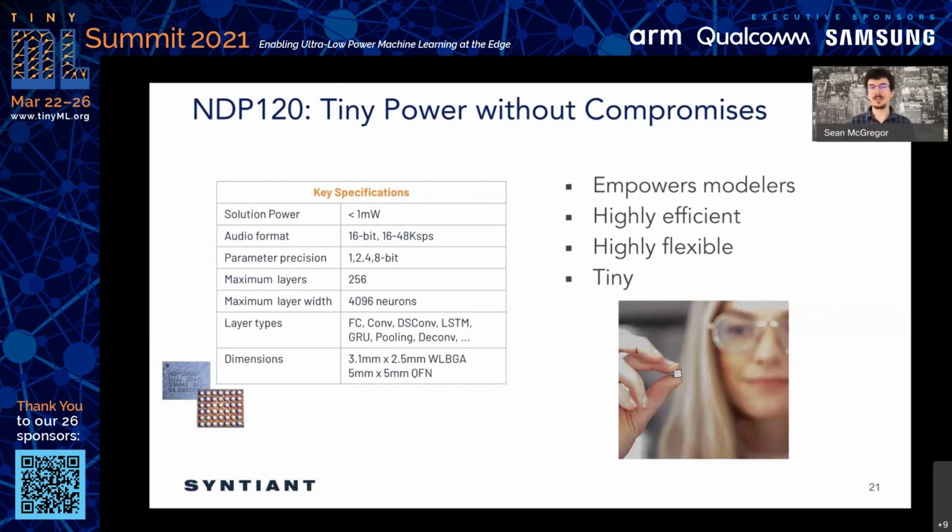If you find that you want to increase the model size to use a little bit more of the footprint in the NDP 120 that's in there, you can say the input layer runs at 8 bits, which input layers often need to be at higher precision, and then you can push towards lower precision in the later parts of the network. Basically it's opening the design space, even if you have a model that's trained on the NDP 100, and you can do a lot of clever things in it that I'm quite happy about.